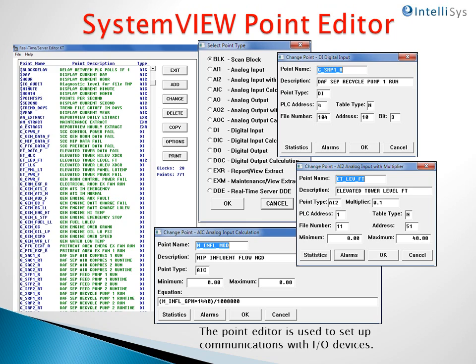We also are showing an analog input calculation. In this case, we're taking a flow, which would be in GPM, multiplying it by 1440 minutes per day and dividing by 1,000,000, giving us a value of MGD, or millions of gallons per day.